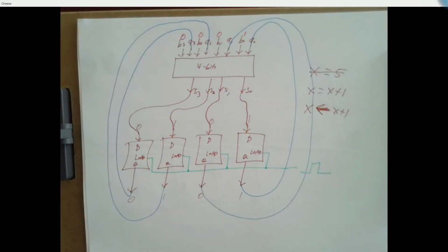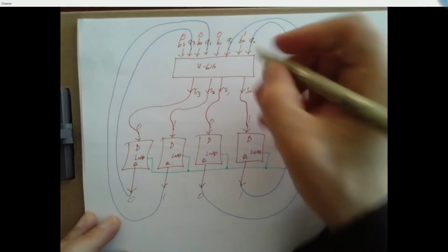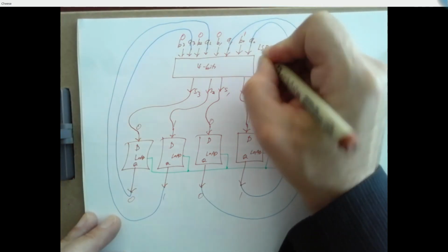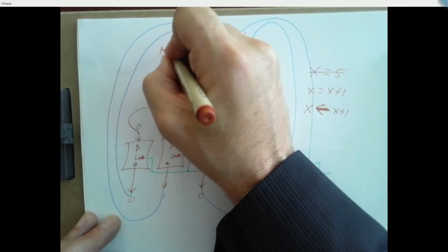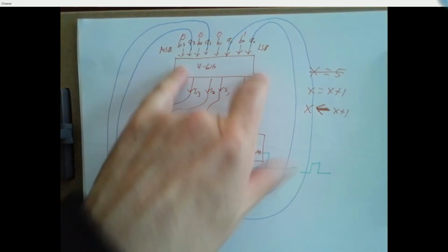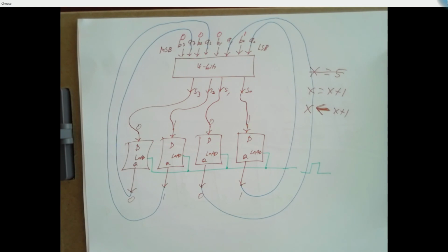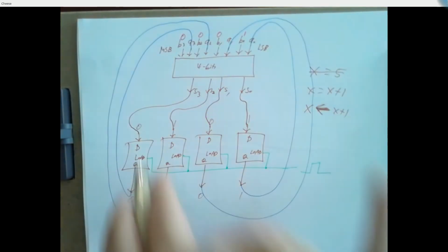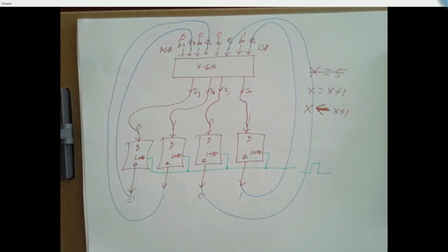Yes? So how do you know what wires to connect, like in what order for the 0, 0, 0, 1? Is it just the binary one? We have to assume what's the least significant bit and the most significant bit. So if this is least significant, then 0, 0, 0, 1 would be 1. But you've got to have that understanding, and this is not always the way it works. There's something called big endian, little endian, and when computers started talking to each other, this caused a lot of hassle. Some computers work one way, some work the other way, and they couldn't always talk to each other.